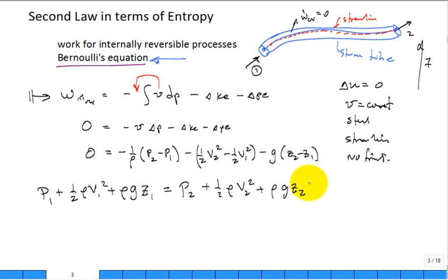A subscript for your second Z? Pretty much it. I'm missing a second subscript for what? Oh, no, it's right there. This is V2 right there, yeah. And so basically you could have cut here, you could have cut there. What you find is that something's conserved no matter how long that stream tube is, as long as it's the same streamline that it's covering, same packs of fluid coming in and out. And so Bernoulli's equation is a conservation of mechanical energy equation for flowing fluid packs.